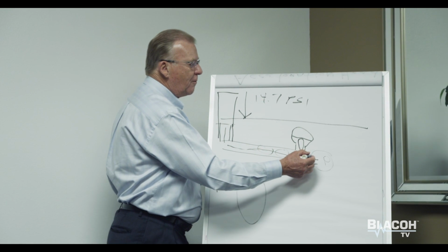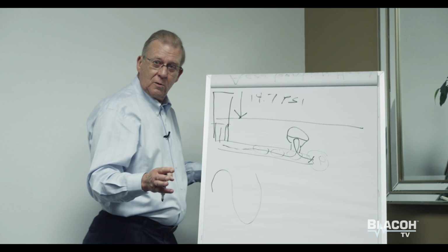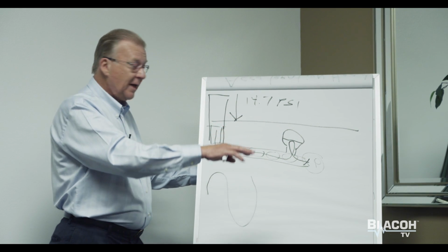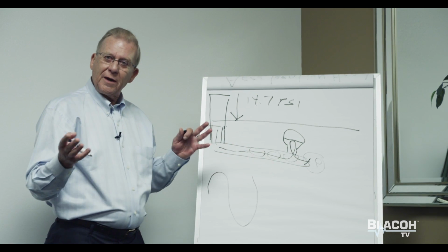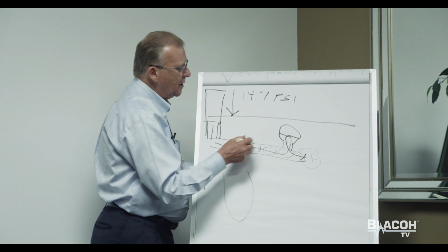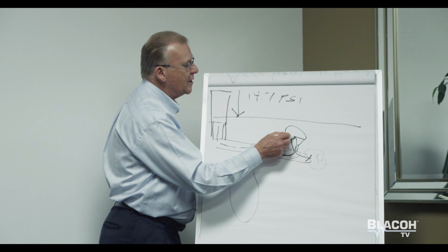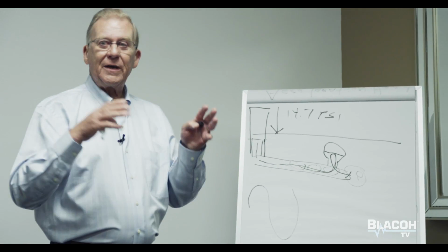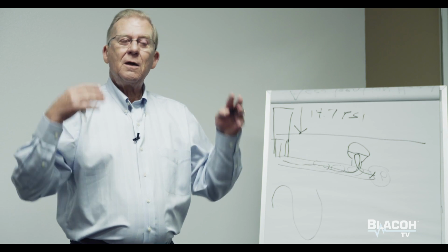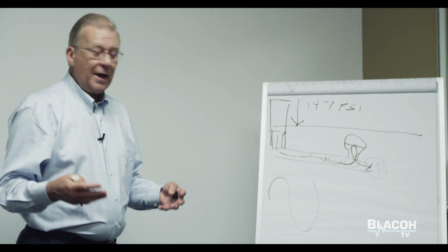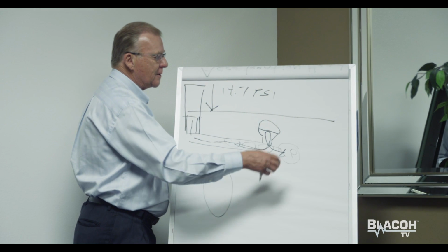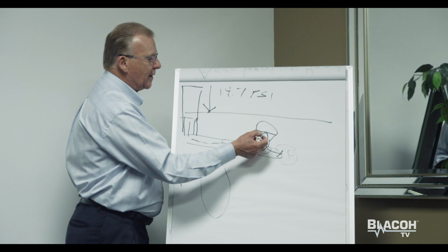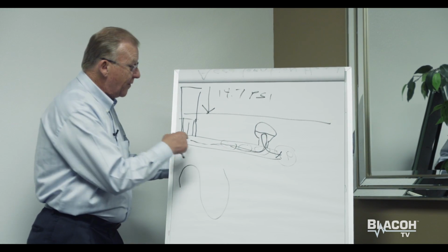So that when the valve balls on the inlet of the pump close, instead of this liquid continuing to move because it's under acceleration, slamming in the check valve and creating a big pressure spike, now the inlet valve balls close, the liquid is cycled or accumulated up into the dampener. The acceleration is decelerated at a controlled, slower speed, so no pressure spike occurs. And we've accumulated liquid again right here, so that when the valve ball opens on the inlet stroke, liquid is immediately available, and this stays in motion.